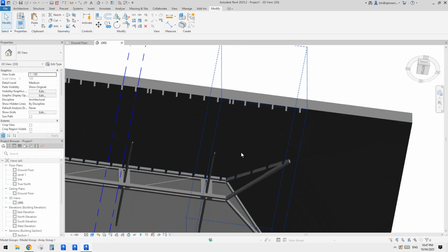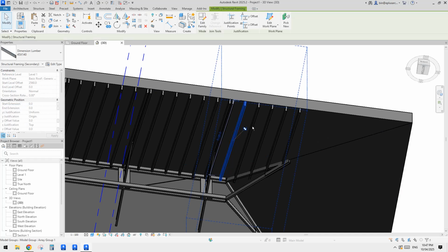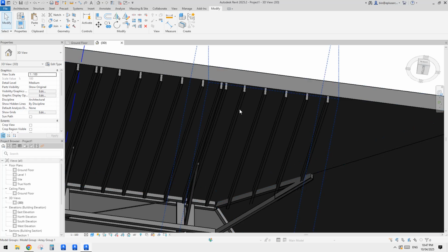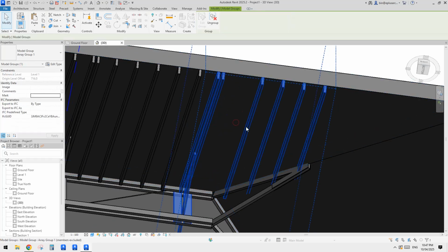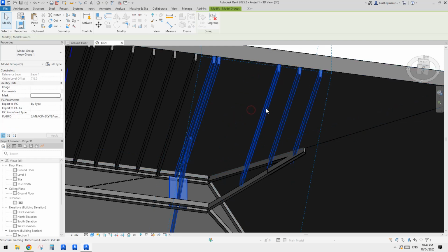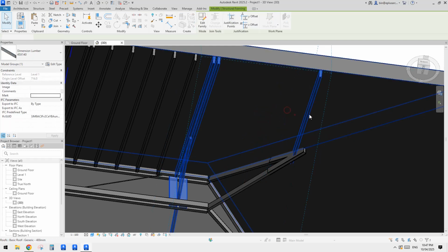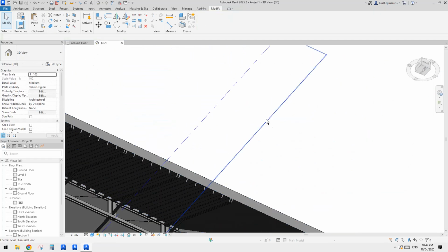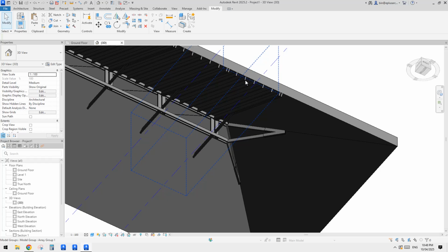But for this one extra, actually, we can just try to tab select these. Because there are only 5, right? So we just need to tab 5 times. Oh, hang on, there's no option here. That's fine, let's just do it again. Tab, select, and just exclude that element. So see this one? Exclude in this group instance. Which means they are no longer there. So we still have this group, but in this group we won't have these 5 members.